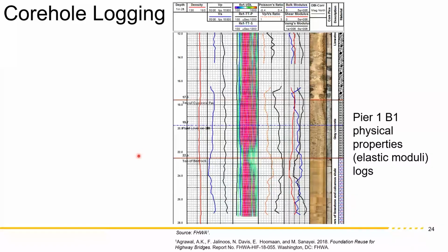So we're looking at the time difference as the wave travels up the core holes, so we get the velocities in place. So we get a full waveform, just similar to that cross-hole sonic, but it's not a resonant signal, so we can pick the compressional wave and shear wave. So we can pick the velocities, compressional wave velocity and shear wave velocity.